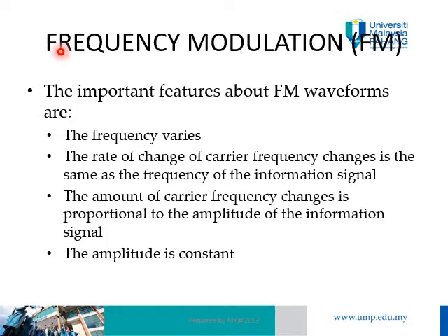So in frequency modulation, FM, the important features about the FM waveform are: first, the frequency varies or changes, but the amplitude remains constant. Second, the rate of change of carrier frequency is the same as the frequency of the information signal.